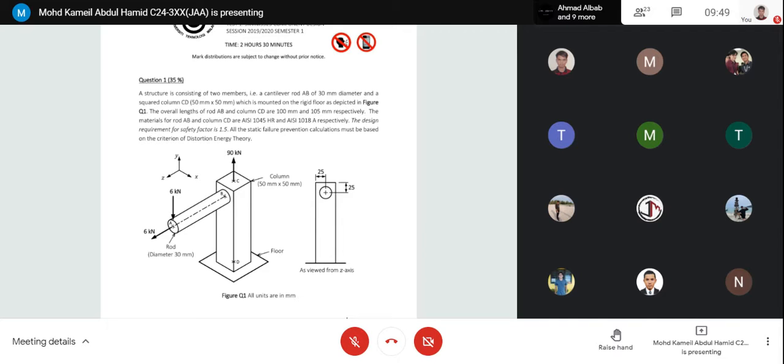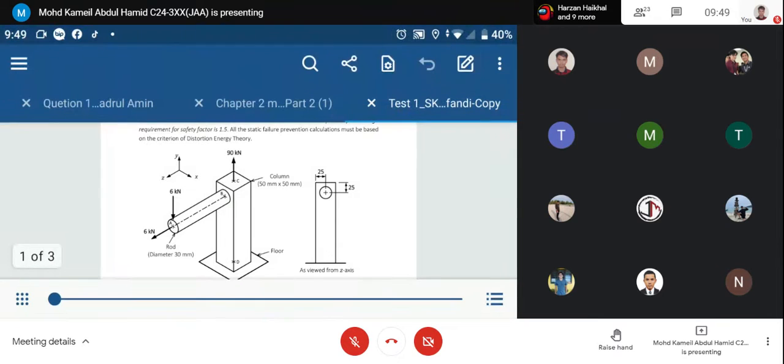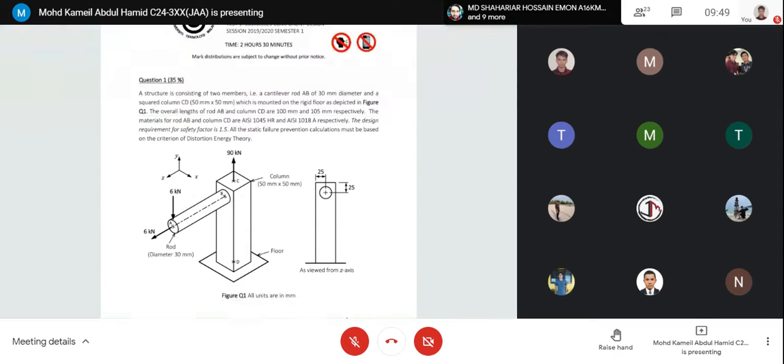Okay, look carefully. From the 6 kilonewton vertical load, which is downward, you will have a reaction, say RBY, pointing upward to counter the 6 kilonewton downward. And then for the 6 kilonewton axial load, you have to counter that too. You can label it, for example, RBZ, in the Z direction to counter the 6 kilonewton along the Z axis.